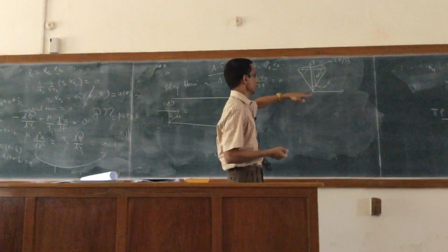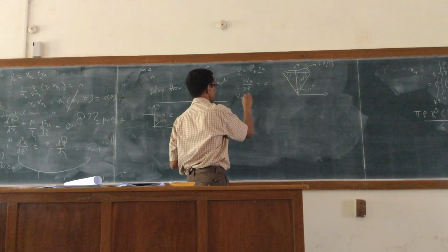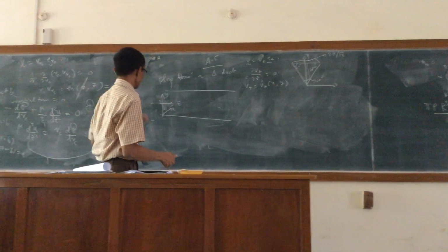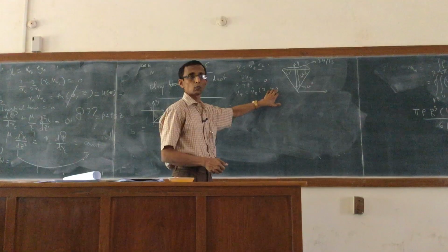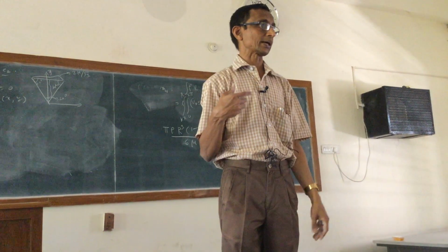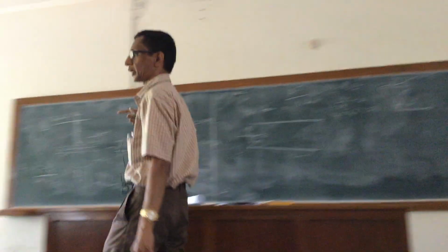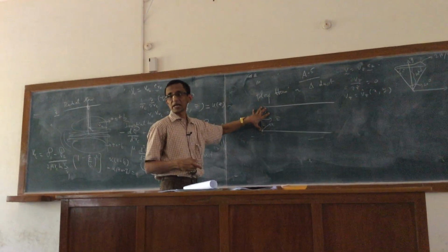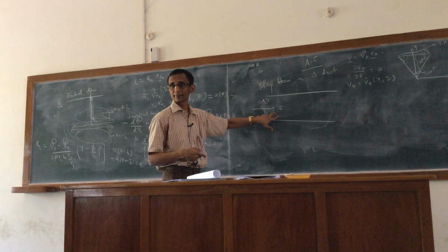Coordinate system, right? So this would mean that Vz is equal to Vz of x, y. Of course, there the x was this direction, so we said neglect the dependence on y. I pointed out that if you analyze the equation of motion through a dimensional analysis, you would find that that is justified if the width of the channel is much larger than the height of the channel. So we can neglect the velocity variance in that direction. Here that direction is x, right?